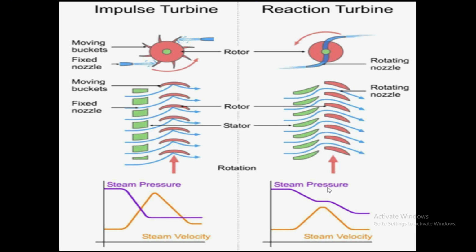The tips of the strips are extremely thin so that if rubbing occurs, the tip gets worn away without damaging the shaft. So these labyrinth seals do not prevent complete leakage of the fluid. They are effective only in reducing the leakage. Complete leakage prevention is done in association with other seals such as carbon seals described earlier.